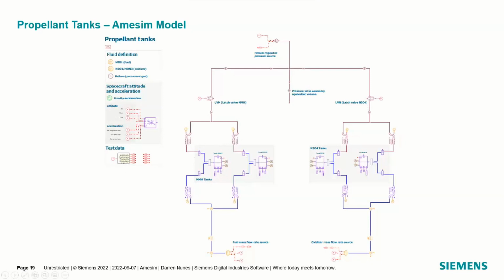And the gas flow through those latch valves, you see these lumped. They're what we call a modular piping system. You can do individual sections like you saw in the first model where we have our bends or our different discretized pipes, or it can be lumped into this one approach, but it still takes that discretized level analysis underneath it, and you can get that modular capability.